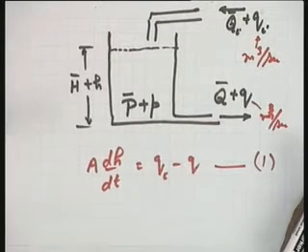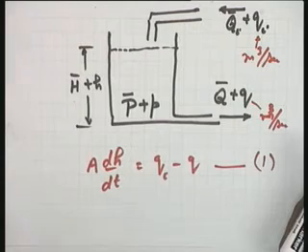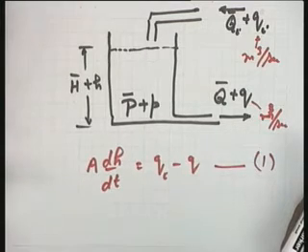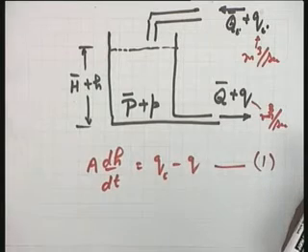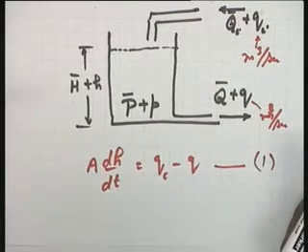Instead of going to the basic parameters of the flow system again and again, when we come to control systems application, I will be concentrating on the two parameters, the hydraulic resistance and hydraulic capacitance, the terms equivalent to electrical resistance and capacitance. So, for any situation, the time constant will be given by R into C, where R is the hydraulic resistance and C is the hydraulic capacitance.